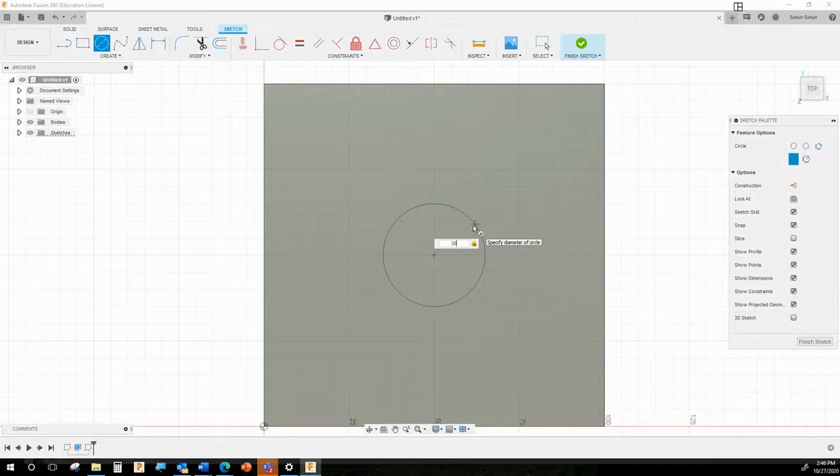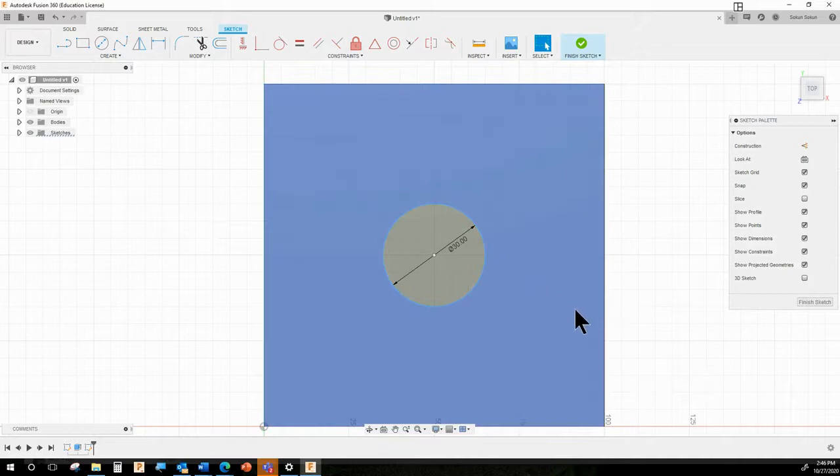And again, this is the hardest thing people have, I think, with beginners. They want to use their mouse to make it exactly 30 millimeters and they spaz. So don't use your mouse to make it 30 millimeters. Just start the circle. Doesn't matter how big it is. Just get the circle started and then type in 30 and then click enter and it will create a circle. Okay? Just took a little time to process. And by the way, sometimes your computer is going to be slow. So sometimes just wait for it, like I had to wait for it there if it's acting unpredictably.